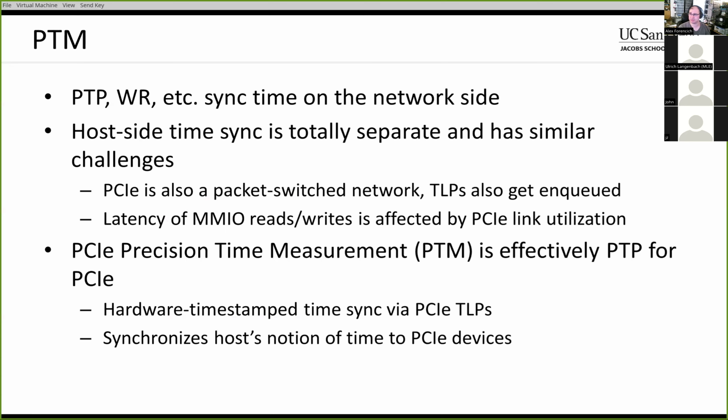So the question is, what can you do about that? Well, not much, right? You have to actually change PCIe to fix that. And standardized in PCIe, I don't know, Gen 5 maybe? This is a pretty recent thing. They added something called PTM, and this is basically PTP for PCIe. So PTM is precision time measurement, and to use it, you have to, in hardware, exchange the synchronization TLPs, right, the PTM messages, and those are going to be hardware timestamped by every component in the system.